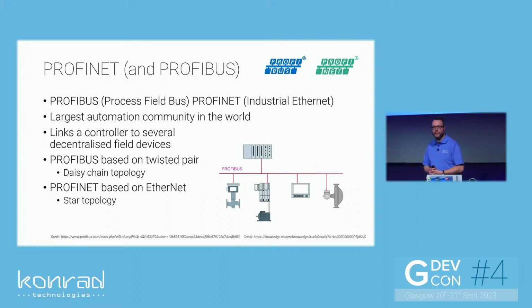And then Profinet is based on Ethernet, so that uses standard network cables. And that's the more modern, more advanced version of that. And obviously with the Profibus side, you tend to have a daisy chain of devices, and I think with Profinet, you get a star topology if you want. It can be more complicated.